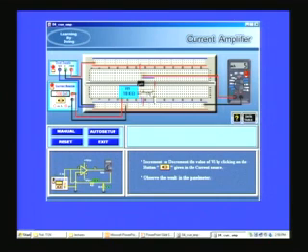It depends on the actual values of the resistors. If there are some variations because of the tolerance, then this factor cannot be exactly 10, it can be slightly less or more. Perhaps that is the reason why you are getting only 10 times and not 11 times. It depends on the actual values of the resistors, which have to be measured using a multimeter. Right. Now let me quickly come down and go to milliamperes.